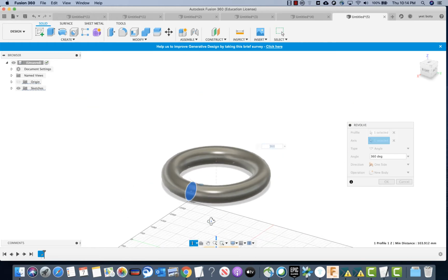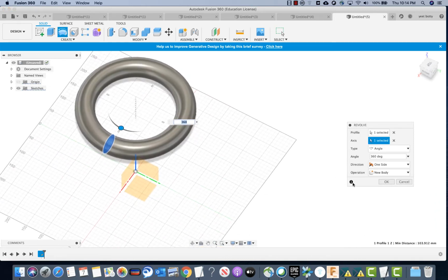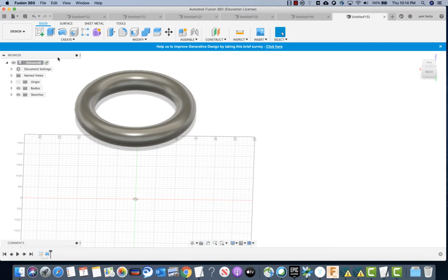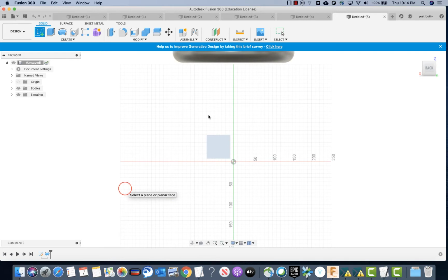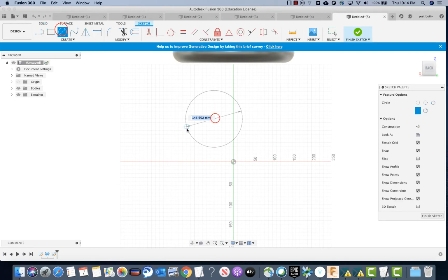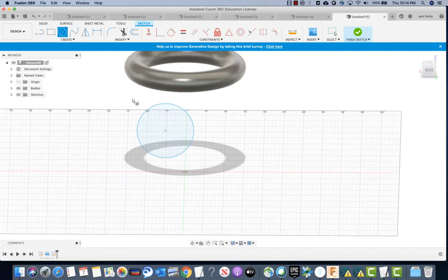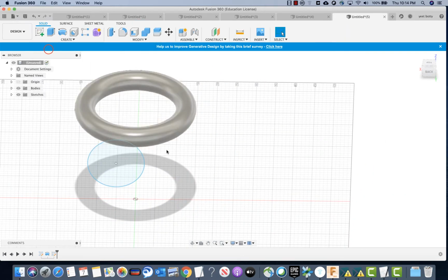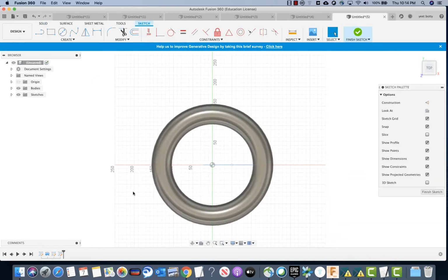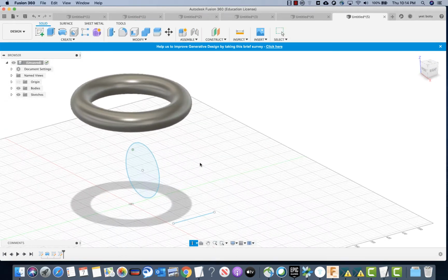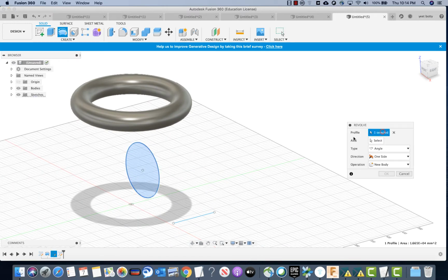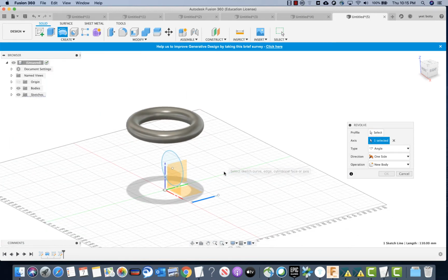I'll give you another example of it. That was we used an axis. I'll just make two lines. Excuse me, one line and a circle. So made a circle here. Finish sketch. Create another sketch, different axis, this one. And I will make a line. Finish sketch. Okay, so now we go to revolve tool, profile, our face, this, and our axis we want it to revolve on is this.